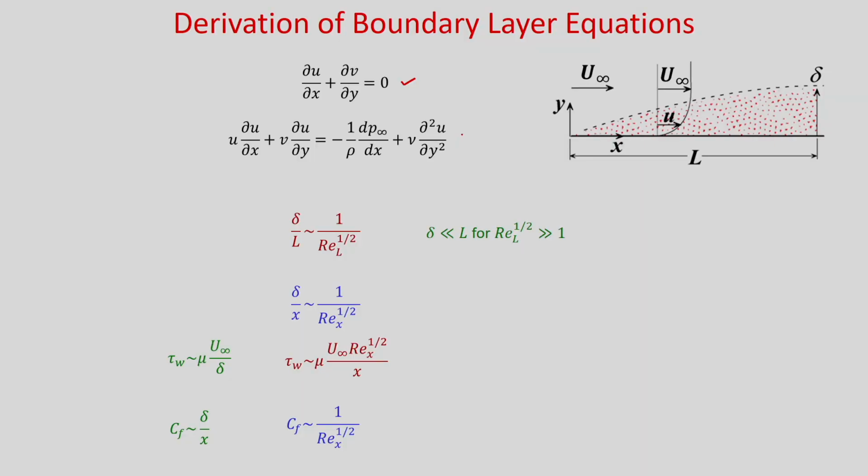Then we used intuitive arguments and scale analysis and we have derived the boundary layer equations. So, you can see this is the continuity equation and this is the momentum equation we have derived, expressing the term P as P infinity, because from the y momentum equation we have seen that del P by del y is of order 0.